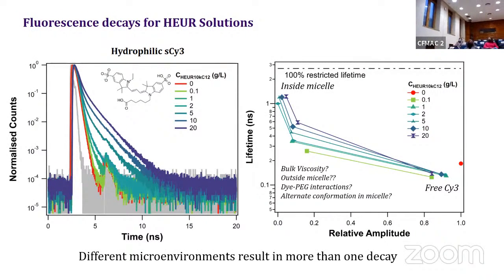Yeah, you see differences, mainly because you can see from the colors that the height changes a lot. You have a film which is a blend of latex and silica, and at the top you have that superstructure which is only silica. So the roughness changes a lot because the height of those transparent structures goes down and up. So yeah, the roughness increases significantly. Okay, it's mainly related to the size of the particle that is on top.